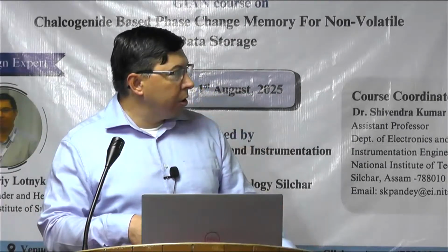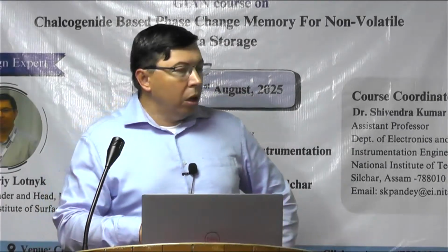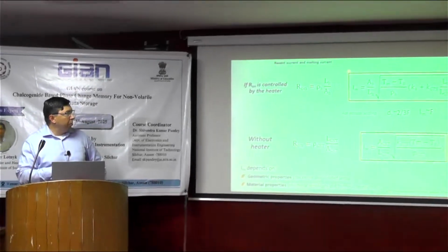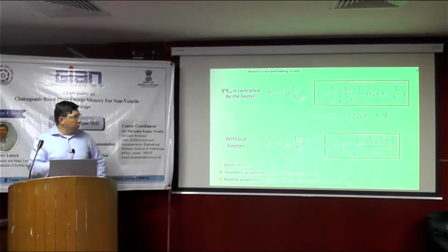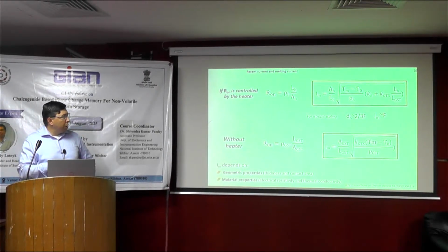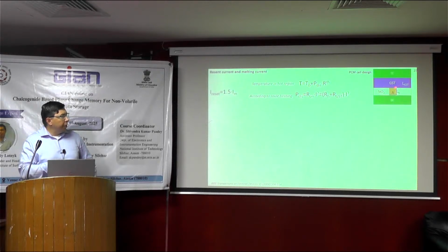So we have considered the effects of contact and material properties on the melting current in two different cases. If you look again, just to recap our knowledge, you see that the melting current is proportional to the AH, and this is AH. This is the area of the electrode, bottom electrode, or its heater in this case, and it's also proportional to the LH, to the length.